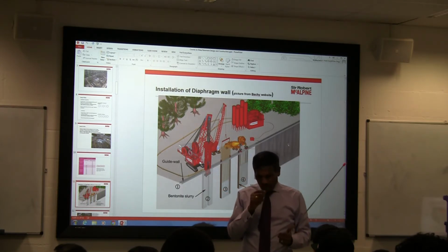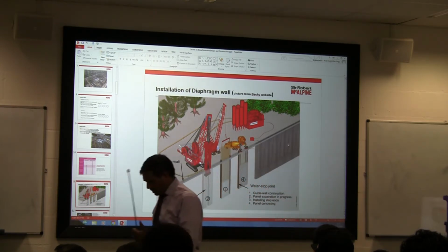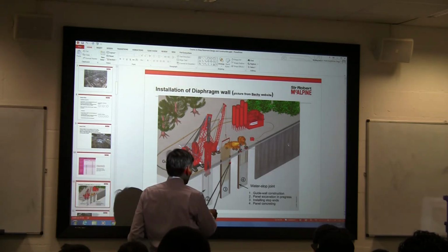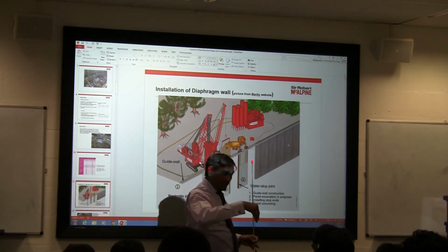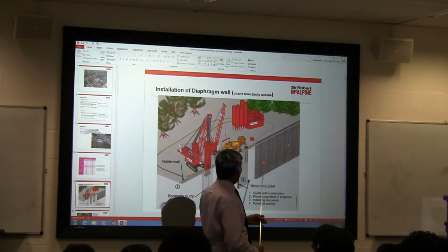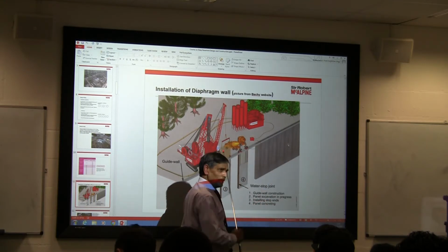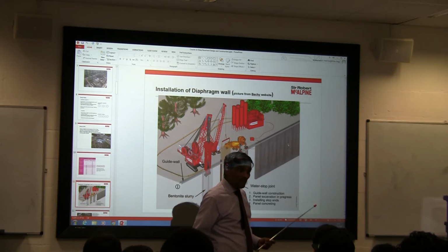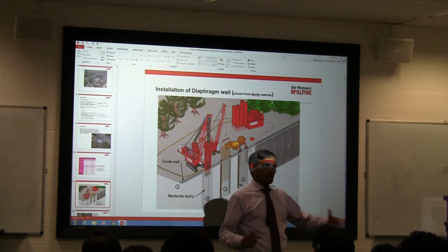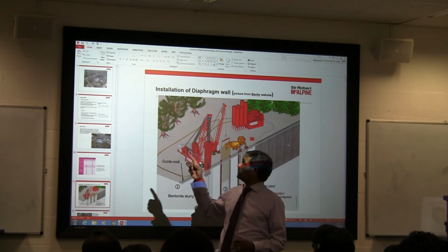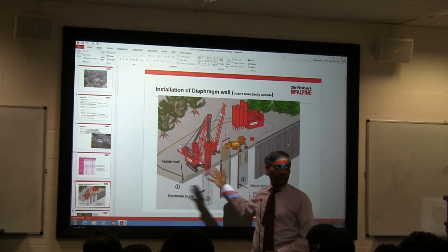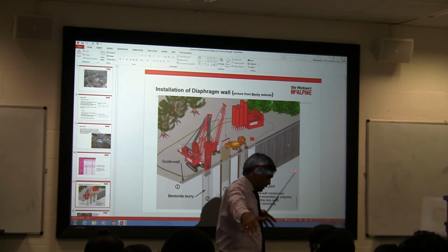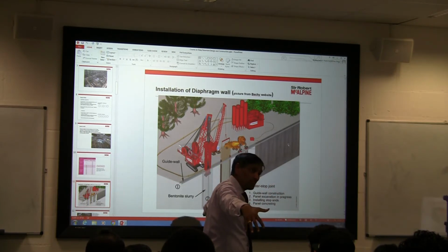The other thing is also important, again, you as a geotechnical engineer should know that if you open a very large hole, although we are putting bentonite in the hole, if you got next door a great listed building, you will have to still think about what is the movement in temporary condition. Because that 7.2 is almost one. So it's about this size, yeah? This is the panel. You are opening ground 1.8 meters, it's about that. It's like a trench you cut.